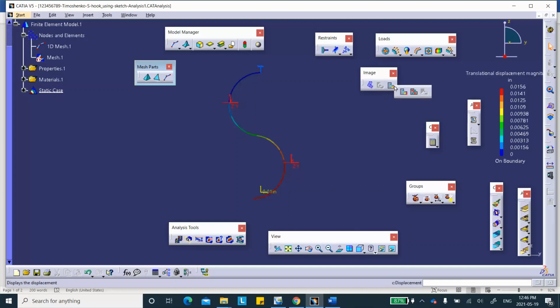It will let you do the principal stresses, but the principal stress that it gives you is axial, which is totally useless. Now, I remember there was some grumbling in class the other day, "Oh, this is useless. Then what's it good for?" No, it's not useless. It's just that if you want detailed information about your beams, you cannot get it from CATIA. As simple as that.